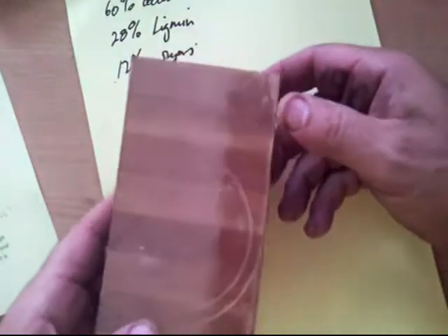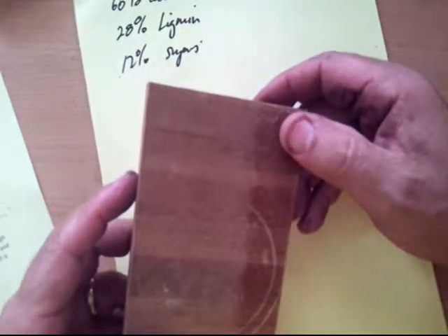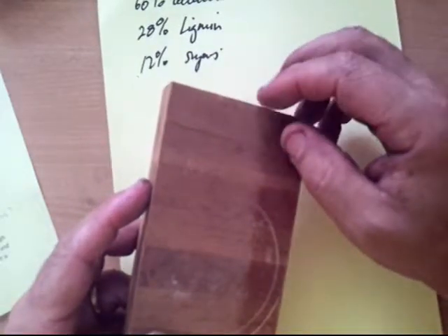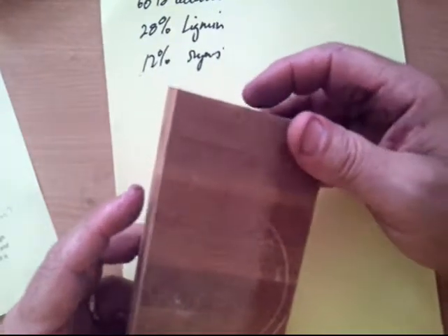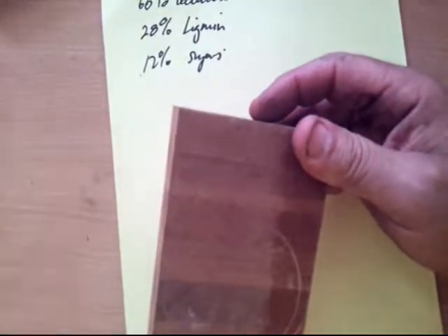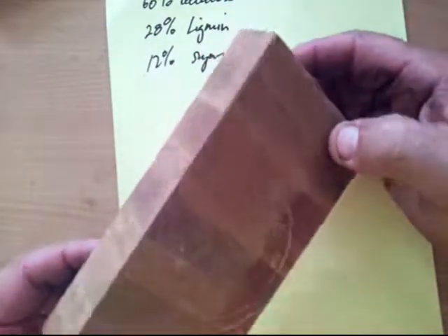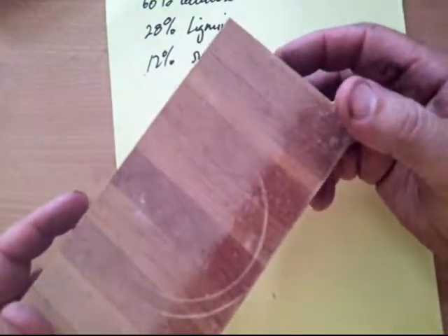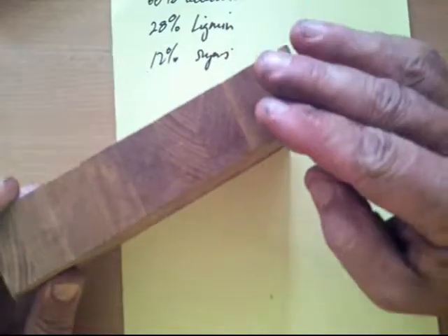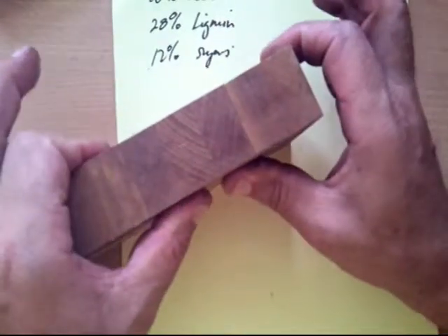Alright, one other problem with wood is that it's anisotropic, meaning that it doesn't have the same strength properties or material properties in all directions. It also has imperfections like knots and grain, etc., which make it inconsistent in its strength properties, and if you get enough water on it, it swells, so it's dimensionally unstable with water.